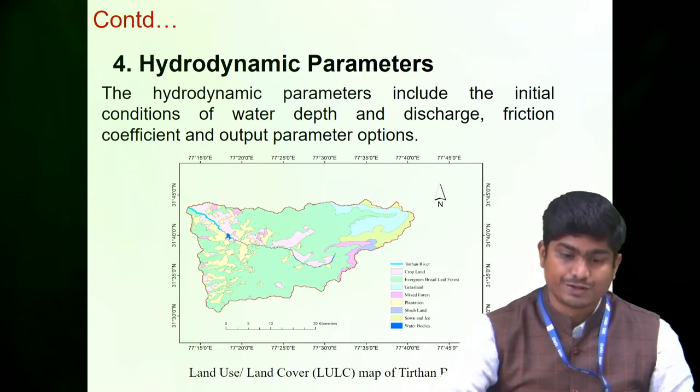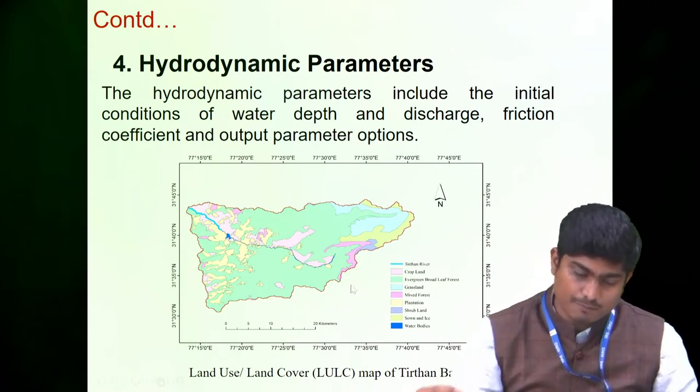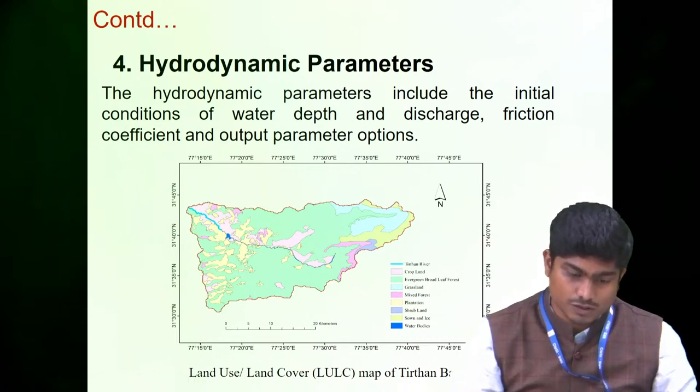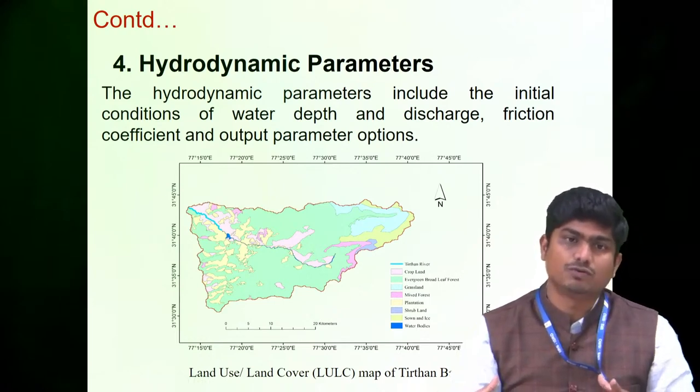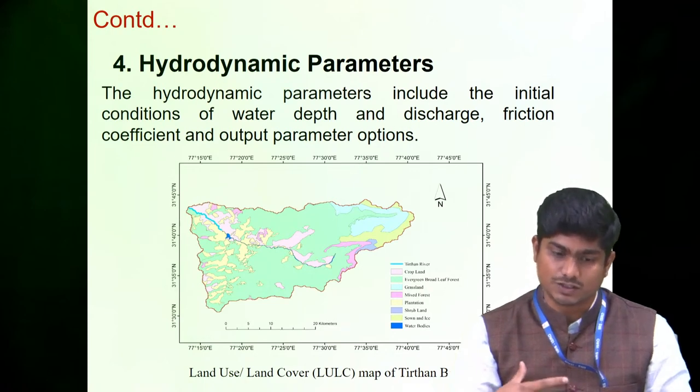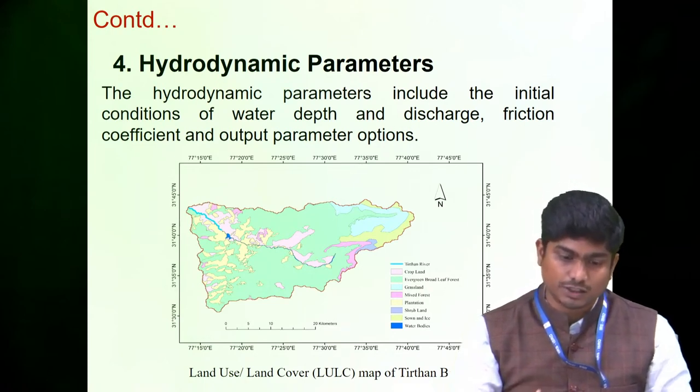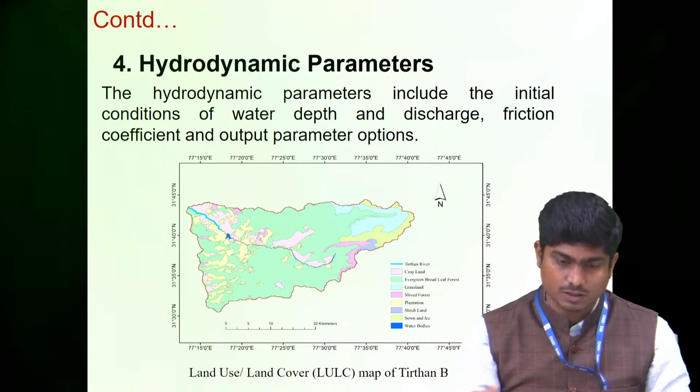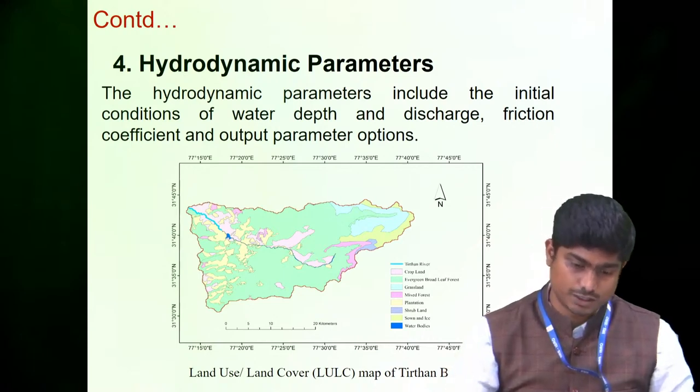So it is also one of the main components of hydrodynamic modeling, because if there is no good match between your observed and simulated discharge at the downstream end, then you try to tune or change this Manning's roughness coefficient.